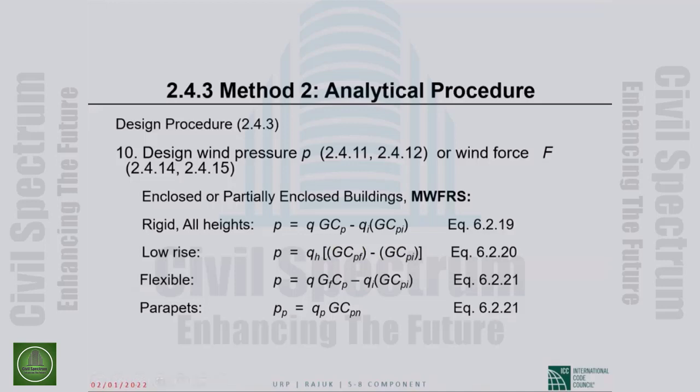The low-rise buildings you can design by that procedure, absolutely allowed. This is for any height. But there is this low-rise analytical procedure, the specialized thing that I skipped. There is no q sub z anywhere. It is q sub h on all faces. And instead of G and C sub P separate, we are given G times C sub pf lumped together in tables.